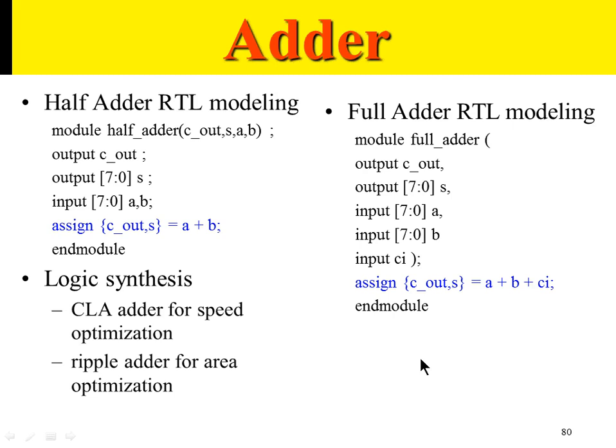When you do hardware design, after Verilog, if you remember the methodology that we have seen, after Verilog coding and functional verification, we follow it with the synthesis step. Synthesis is a step which will convert your Verilog code to a gate level netlist or hardware netlist. That is the first step in hardware design after Verilog coding.